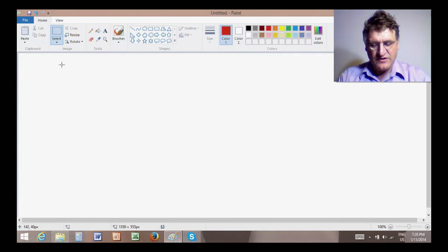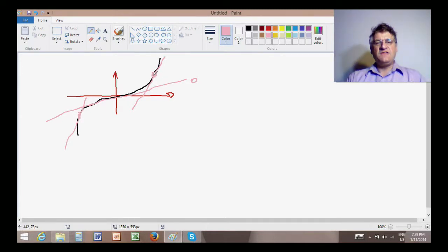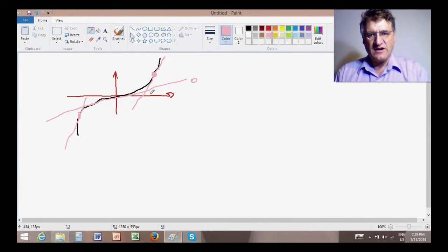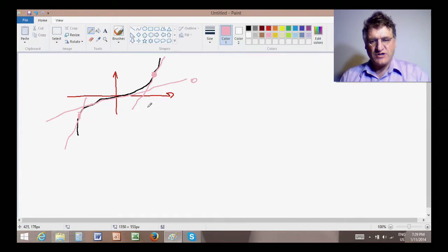Now, the simplest way you can deal with nonlinearities is by saying, well, so my nonlinearity is appearing as such. Okay. What I'm going to do is I'm going to linearize it around the operating point that I'm interested in. In this case, 0. In that case, some positive point. In this case, some negative point. And in the vicinity of this nonlinearity, we can indeed approximate its behavior by the corresponding tangent line. This is a completely standard procedure that really makes life much easier.